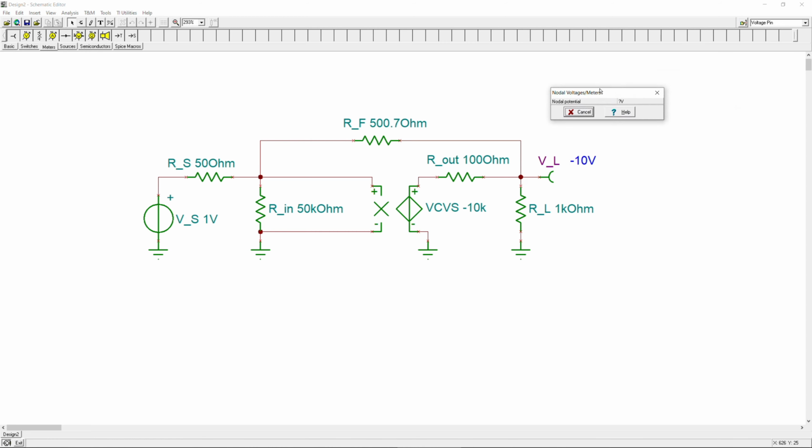That's exactly the situation. So this is really the situation when you have this resistor here. That extra resistance here is really needed. So extra gain actually, because the loop gain here is not infinite. So that causes that you need a larger feedback resistor here instead of 500.